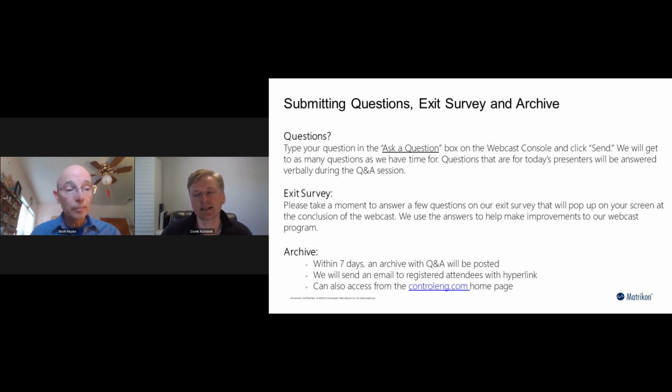Now, again, as far as choosing what you're going to use, you really would have to look closely at what your end goal down in the future will be, because OPC UA travels over MQTT just as well. MQTT is a transport. For people who don't live in the protocol world, or at that level of protocols rather than applications that sit above them, that's sometimes confusing. But a protocol travels over a transport.